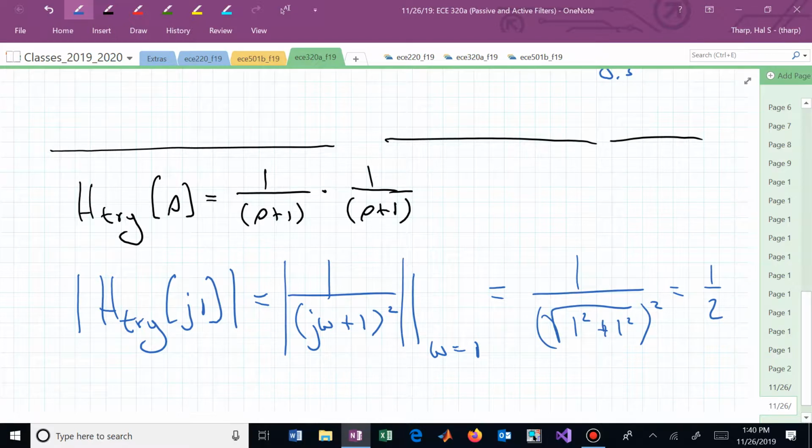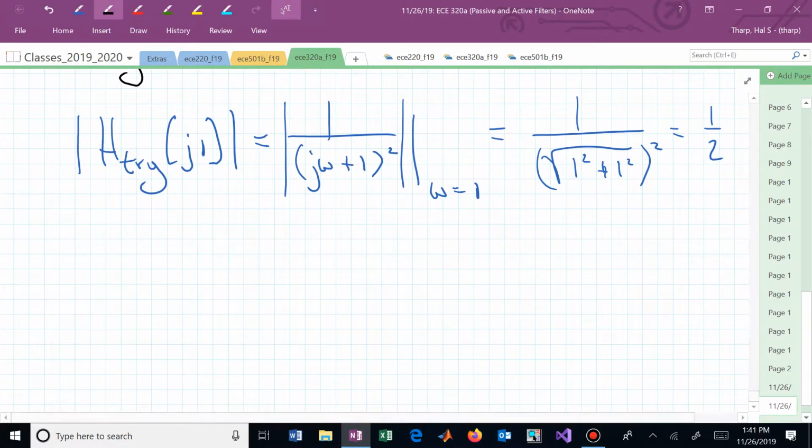So by getting more filtering, not arbitrarily, but by trying to add in cascade the same filter stage together, just keep stacking them up, because that will give me more roll-off, I thought it would give me the same behavior. In fact, this now compromises our magnitude.